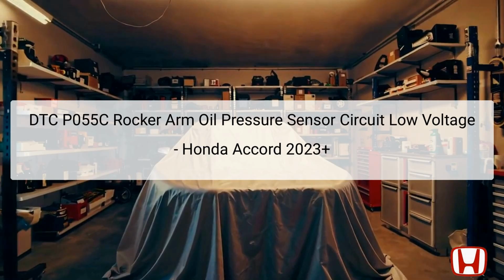The rocker arm oil pressure sensor is critical as it monitors the oil pressure supplied to the engine rocker arms, ensuring proper lubrication and operation. When the sensor detects low oil pressure, it sends an electrical signal to the PCM, which processes this information to maintain engine performance and efficiency.